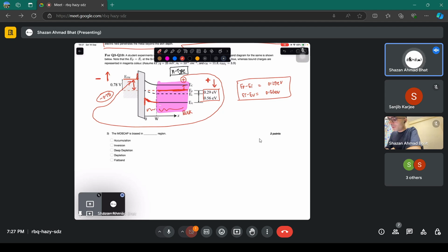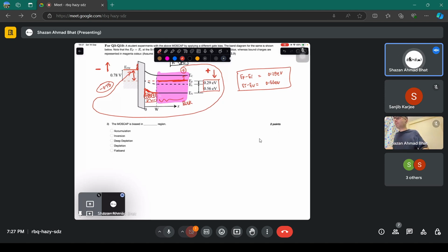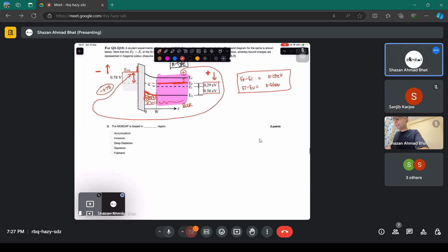So only positive charges are left now. Okay, these are the depleted charges. That's why it's called depletion. Depletion means you depleted or you made it less of something. You took away electrons from positive charges, you depleted it. So that is why this particular mode is the depletion region of the N-type, because you have depleted it. That's what it is showing.